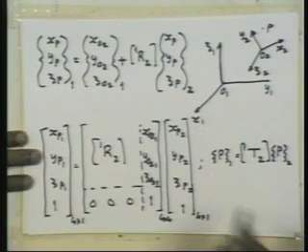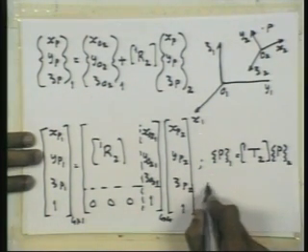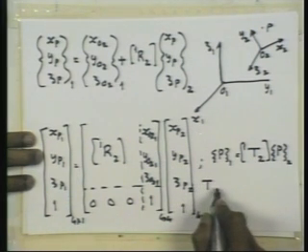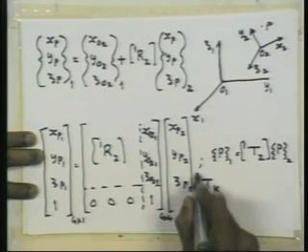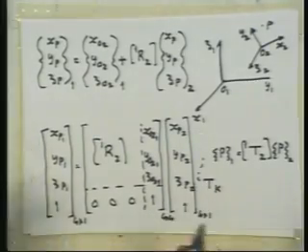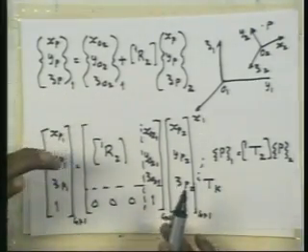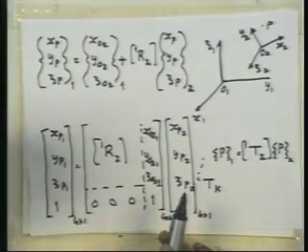And this has the property that if you want to express some k with respect to i, remember this transformation matrix contains the information about position and orientation because it has the rotation matrix and the offset of the origin. So that could be specification for position and orientation.